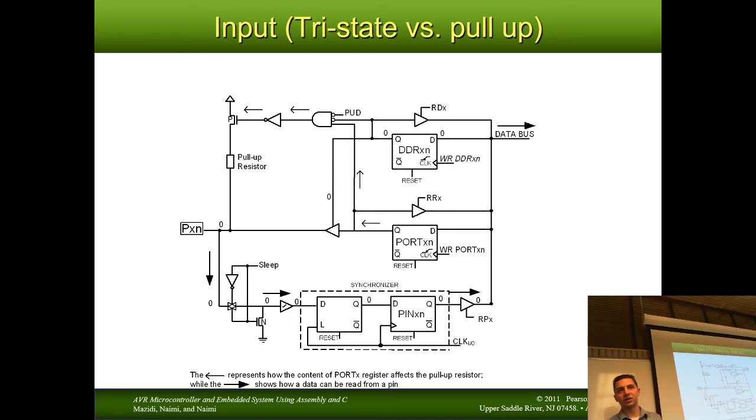Off this data bus, off camera, that's everything else in the processor. There's tons of other stuff in there. But for the moment, all we care about is these 3 registers. This synchronizer runs on the I/O clock, 16 megahertz or 20 megahertz, whatever you're running the processor at, and is there mostly to deal with glitches.